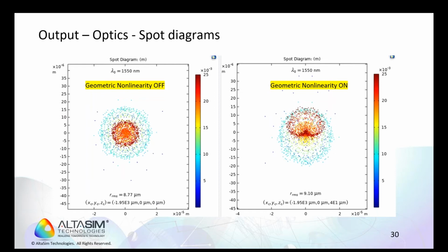This information is going to enable the designer to locate the focal plane, including the deformation effects. The designer is also going to be able to visualize the actual spot diagram and make changes to the optics to make that spot geometry look more like the spot on the left. For those of us with less than perfect eyesight, I think about this diagram as showing the astigmatism of the system.